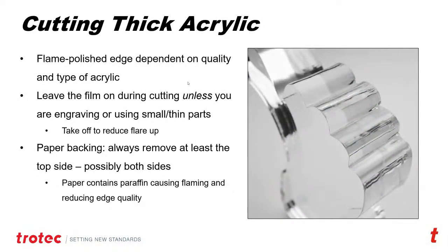Thick acrylic can be difficult. If you have enough power, you can definitely do it. And so this is more than an inch thick piece of acrylic. High wattage is necessary, but flame can be a tricky one. You want to make sure that you do it properly, like leaving the film on the surface when you're doing it. It can reduce the flare up, and I typically like to leave the film on at least the back side, but not on the front side. But you've got to be careful with especially paper backings, because it can potentially actually cause flare-ups. Make sure you have enough power on your laser system if you are looking to cut very, very thick acrylic.